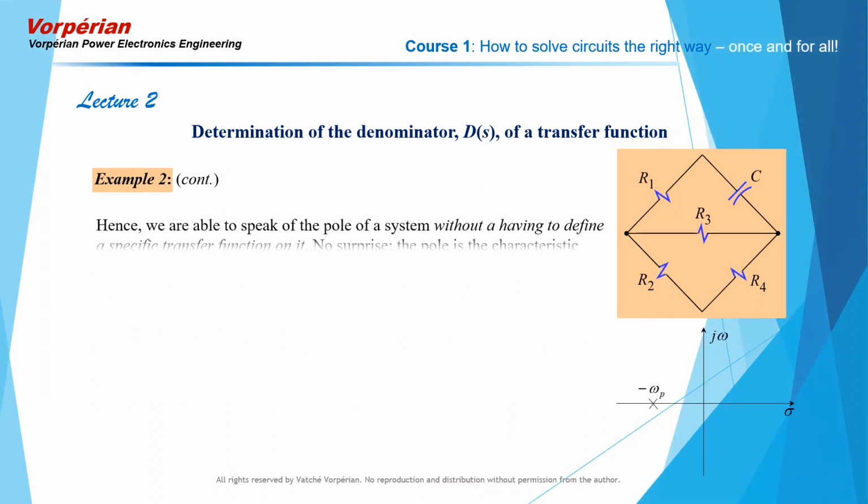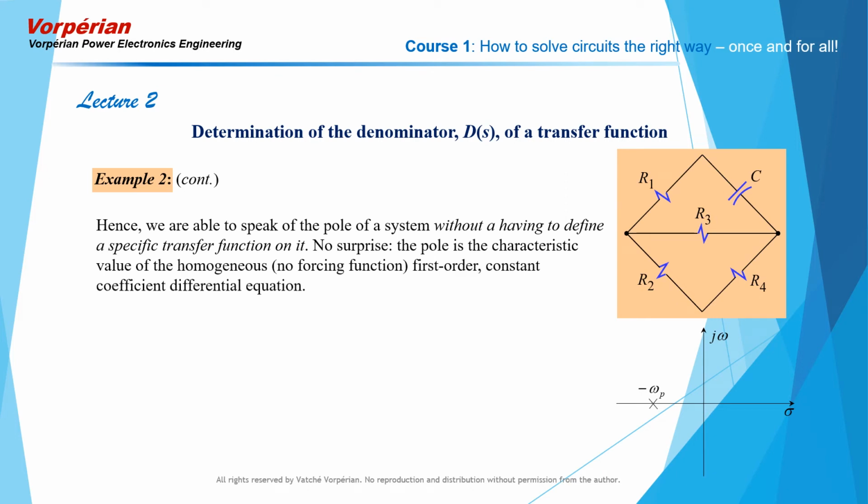To reiterate then, we are able to speak of the pole of a system without having to define a specific transfer function on it. No surprise here, because the pole is the characteristic value of the homogeneous no-forcing function, that is to say, first-order constant coefficient differential equation.